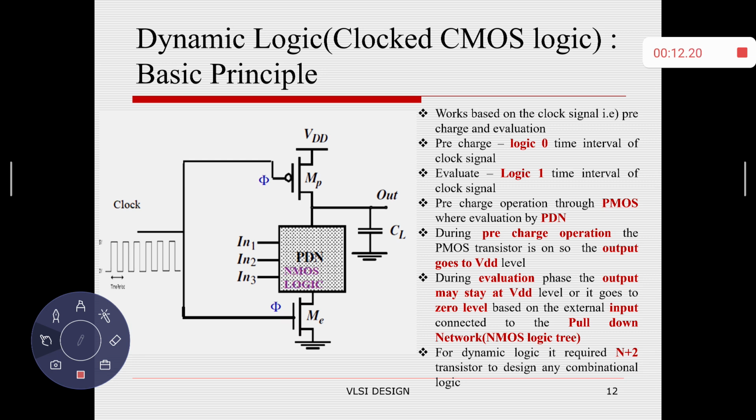So what do you mean by pre-charge? Pre-charge means only the PMOS transistor is connected, whereas in the evaluation phase, according to the external inputs you have connected for the NMOS logic, the output will be evaluated. It will be evaluated to the VDD level, or it may be evaluated to the 0 level, according to the inputs connected for the NMOS logic.